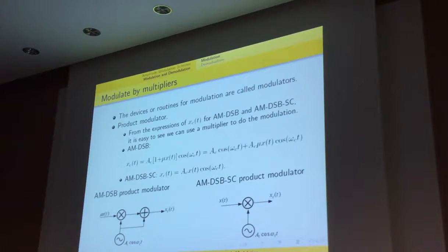And don't even mention the multiplier. The multiplier itself is a three-port component. That means there are two input ports and one output port. Generally, it's very hard to implement. Why? Because a multiplier, in most cases, is a nonlinear element. It means that you will produce a product of these two inputs plus some other components. So practically, with a practical multiplier, you need to add some filter to reject those high frequency harmonics and only keep the product term.